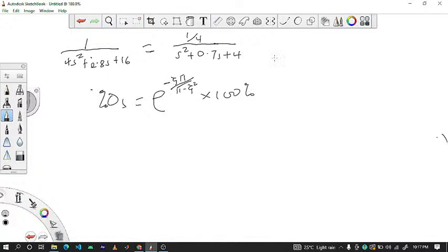If you look at your s-plane, a plot of j omega against sigma, the peak overshoot is just a function of zeta. So wherever your damping ratio is constant, your peak overshoot too is constant.